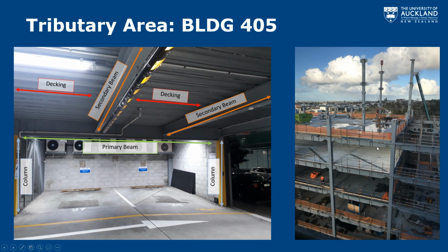And so, again, to orient yourself before we start looking at the building plan, we have the metal decking, which is running in the north-south direction. So north is over here for the building. You can see here under construction the secondary beams. Those are spaced at even intervals.